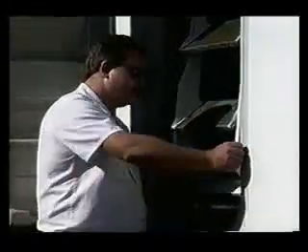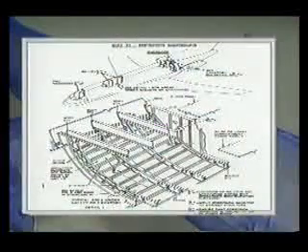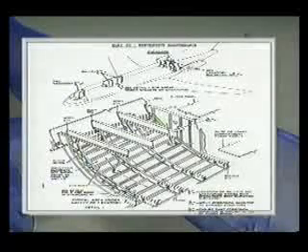A good time to evaluate the effectiveness of your corrosion control program is during heavy inspections. During these heavy inspection periods, an inspection similar to the baseline inspection should be performed, which utilizes the original aircraft checklist of potential problem areas. If there are no reports of corrosion during these inspections, then you can be encouraged that your corrosion program is effective. If, however, you discover any serious corrosion on these subsequent inspections, the corrosion program must be revised to eliminate the deficiencies. Revisions to the program should include the addition of any new corrosion trouble spots to the corrosion maps.